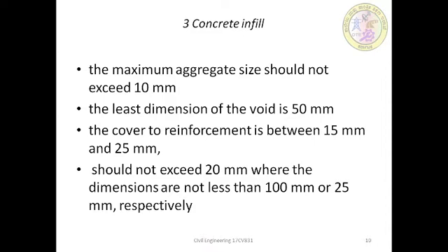In order to ensure the workability and pourability of the infill, sufficient water should be added to the mix. However, in order to reduce the risk of cracking in the infill due to shrinkage resulting from the loss of water into the masonry, an expanding agent may be used. The characteristic compressive cylinder or cube strength of such concrete infill, fck, should not be less than 12 MPa or 15 MPa respectively.